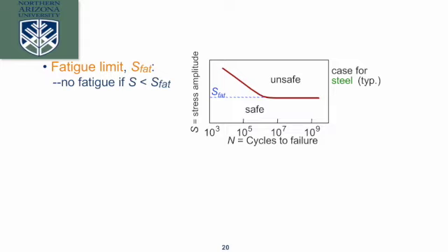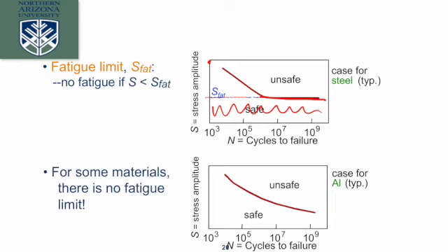Okay? So the idea here is there's a safety factor, right? We test this material. We know that its initial yield strength is up here. As long as we don't stress the material above this safe line here, where the endurance limit starts, if we work in this area, then we're guaranteed that the material will not fail. Okay, and that's called a fatigue limit. Whereas that limit does not exist on things like aluminum because the cracks do not blunt out. So even if we're staying in that same safe area, once this stress crosses this line, the material will fail. Okay, so we can avoid that using the right type of material for the right job.